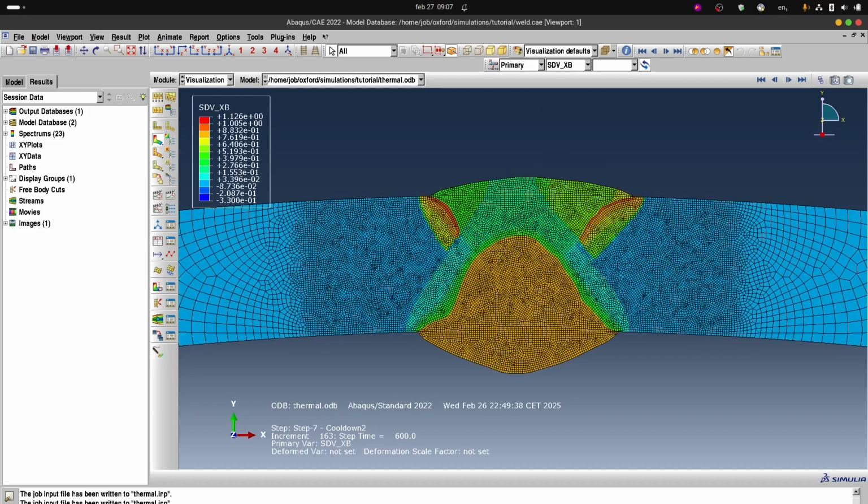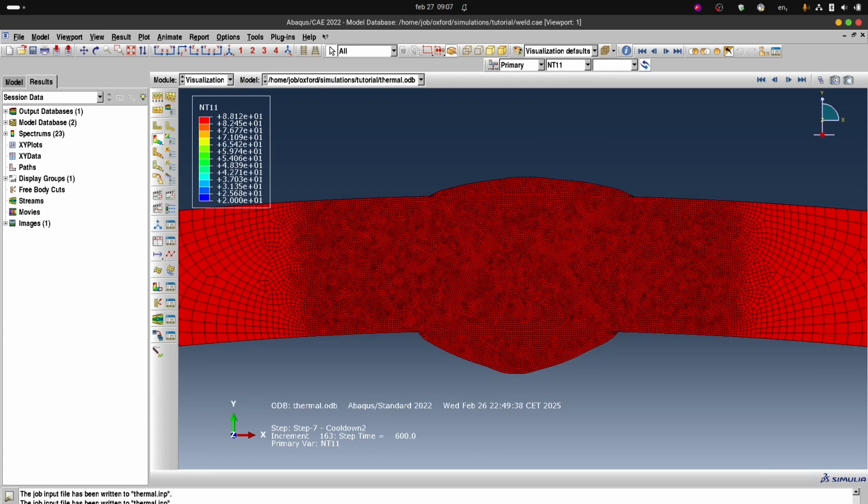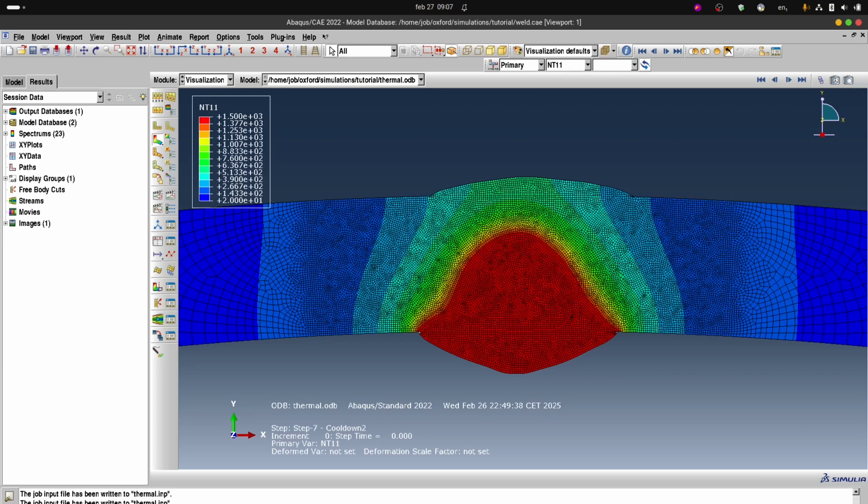And probably the weld has mostly become martensite fraction. Furthermore, you can view the temperature fields. This is at the end of the simulation, it has almost all gone down. Yeah, you can basically scroll through all the welding steps.